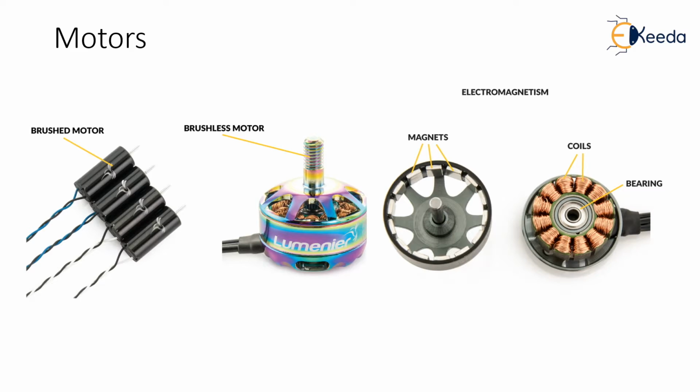When the motor windings become energized, both the motors have coils. A temporary magnetic field is created that repels and/or attracts against the permanent magnets present inside the motor. This magnetic force is creating the repulsive force in the coil that is used to rotate the shaft. There are two major parts for a brushless motor called a stator and a rotor.